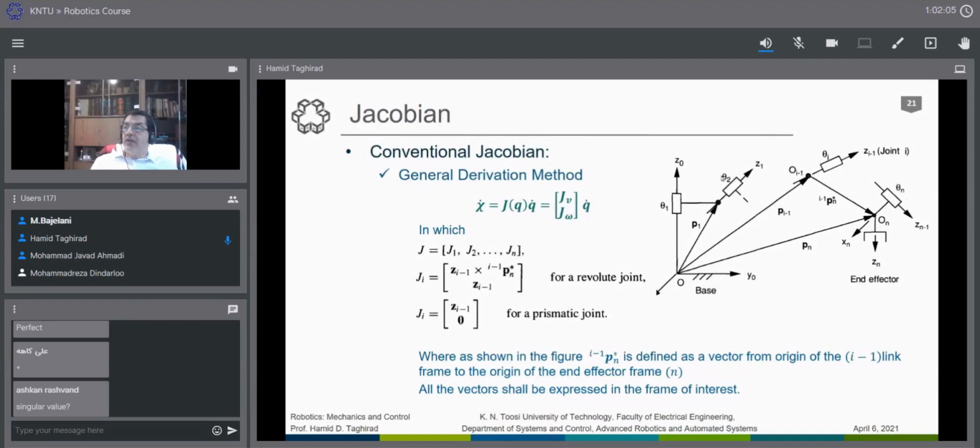And of course, we can represent the Zi joint using the Denavit-Hartenberg method, the conventional or Paul method. Any frame theta 2 is with respect to Z1, theta i with respect to Z(i-1), as you remember. And this goes to the Zn, which is the end effector.